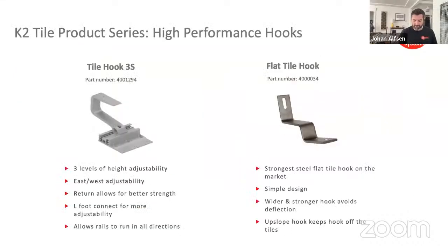So getting into our tile hooks real quick. Our K2 product series, we have a bunch of different tile hooks. As I mentioned, we pull from our international colleagues at K2, and they had some really strong, robust tile hooks in Germany. And tile hooks are used almost exclusively in Europe. And they had the 3S hook, which is an adjustable tile hook, and it has a return on it, so you can use the L foot. So it's definitely more robust, more expensive, but it has so many different features and adjustments.